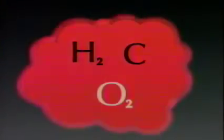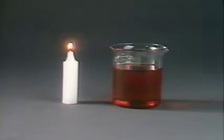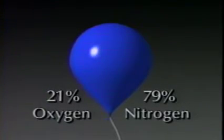Let's take another look at the combustion process to understand the air to fuel ratio. Remember the candle? The same chemical results take place when fuel oil is burned. The oxygen in the oxidation process comes from the air, but air is only 21% oxygen. The rest is primarily nitrogen, which doesn't take part in combustion, but passes through the process unchanged.